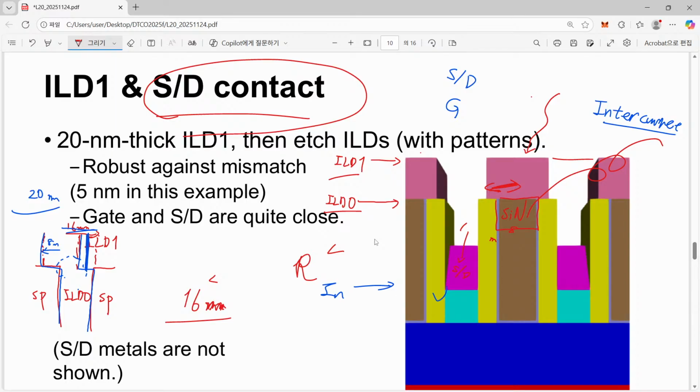Also, quite similarly, in our source and drain part, we introduce this so-called capping layer. And only when we want to use it explicitly, we etch and explicitly remove this silicon nitride and take good access to this one. Usually these silicon nitride capping layers work as the protection layer for our gate, source and drain region.